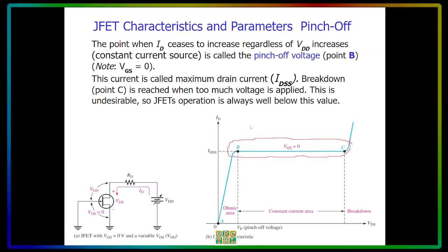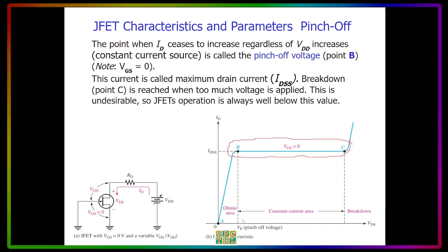So all in all, this drawing or diagram has the VDS on the x-axis and ID on the y-axis, and we have here the IDSS, and the start of the saturation, which we call the VP or pinch off voltage.